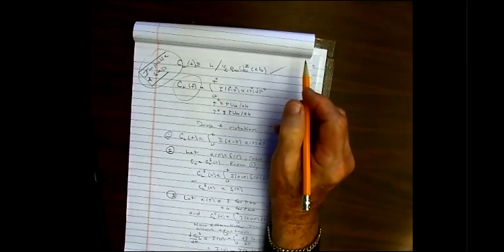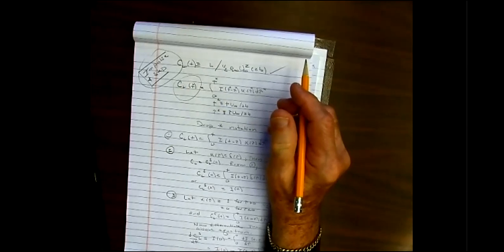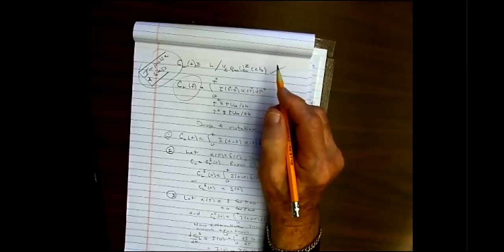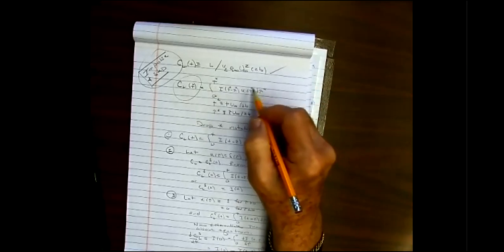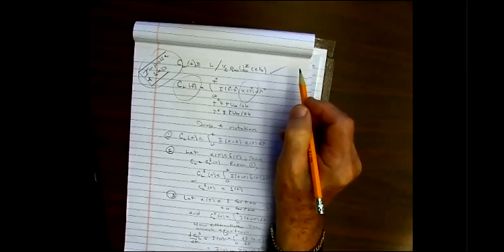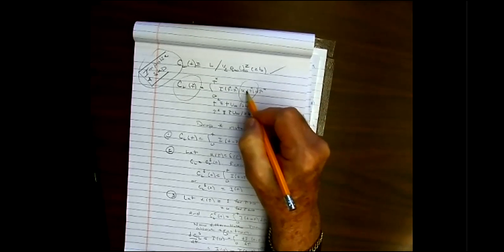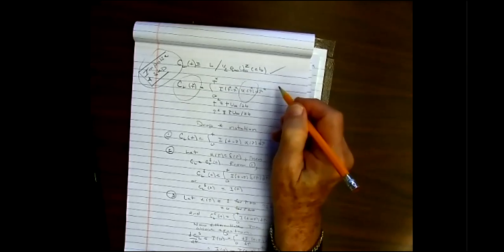In this case, our output to an aerodynamics is, for example, the lift or the moment, or even the pressure distribution itself. I can write that as a linear relationship with respect to some motion variable like alpha or H dot over U or Gust velocity.